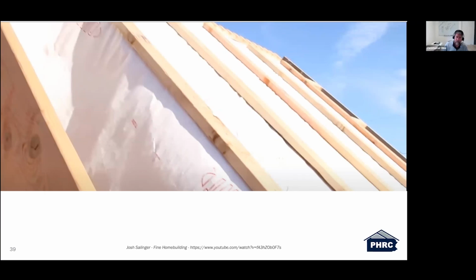these rafters. So again, one thing that I do want to touch on, I was walking through this assembly with an engineer friend of mine, and he'd pointed out that an engineer may have to get involved slightly on this to calculate this connection of the roof sheathing to or through that 2x4 into the rafter, because that roof sheathing isn't being applied directly on top of the rafter. There may be some sort of engineering that has to take place for this assembly to continue on, but it does allow for, I would call it a great way to vent this raftered truss or raftered ceiling.